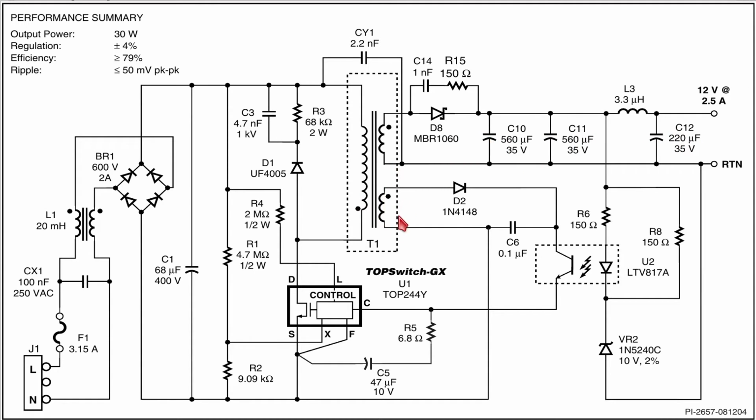And as you see, the secondary winding is then providing the feedback voltage. This is done instead of using the output here as the feedback because we want to have a complete galvanic separation between the primary side, which is at the mains voltage. So yeah, it can kill you easily if something bad happens. And the secondary side, which then should not carry any dangerous voltages. So this is why they are using these two different windings.